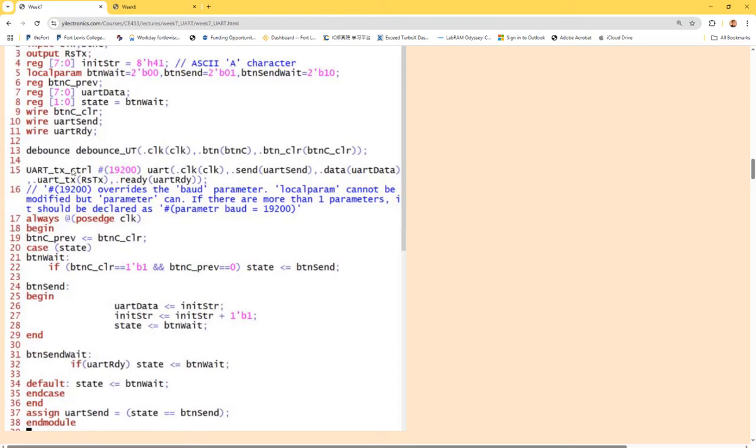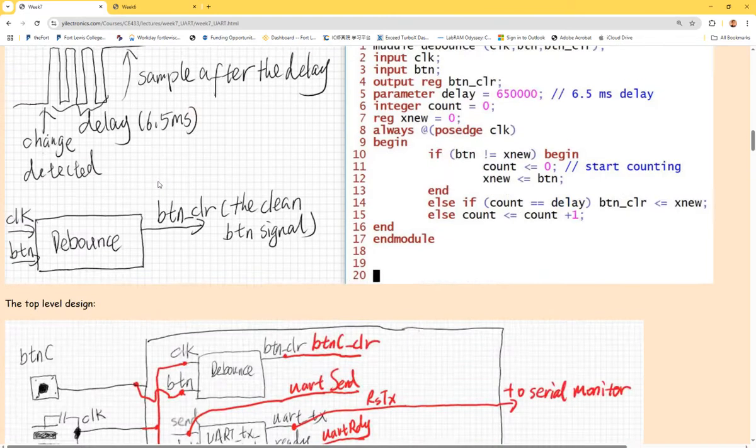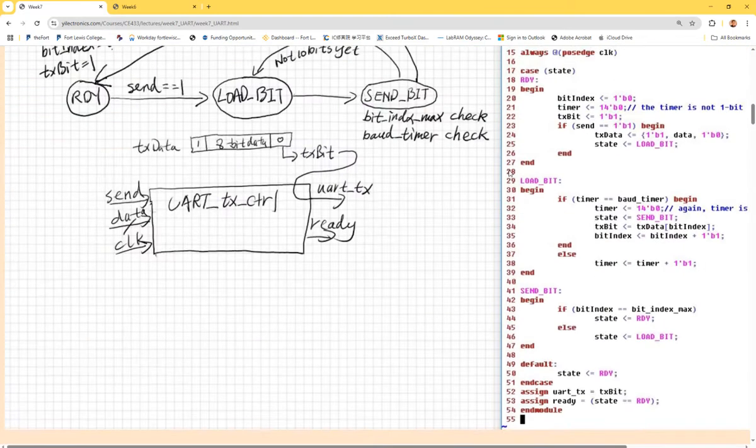It's a chip, it's the IP. Keep it there, okay? And set all the parameters you will probably change in the future as parameters. Then you can override the parameter in the top, but never modify it in that chip. Keep it clean. So go to your TX controller module, which is here.